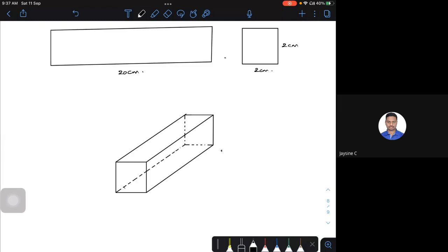Now, here the most important thing is the vertices. Suppose I fix this particular thing. The most important thing we try to do in OpenFOAM is, if I want to put it in the blockMeshDict file, I need to define the reference frame. So if I define this as my reference, I'm going to give this as my y-axis and this as my x-axis. This is a rule I'm trying to discuss. It can be xy or xz, or yz, whatever it may be, doesn't matter.